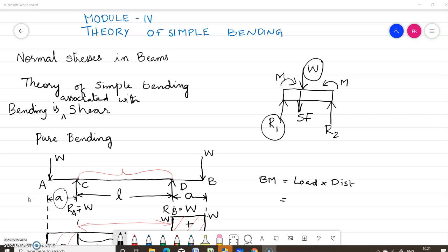So all of us know whenever a beam is subjected to a moment, the beam will bend. So due to this moment, the beam sags or hogs. Okay. It is obvious that due to sagging moment, fibers at the bottom get stretched, and hence we can say that at the lower side elements are subjected to tension, and on the upper side the fibers get compressed, and hence an element in the upper portion is under compression.